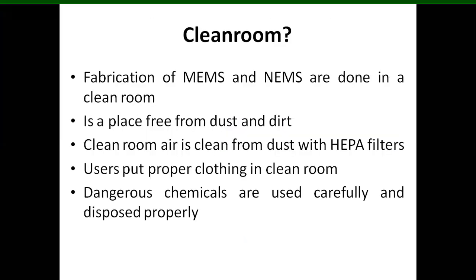Okay, next is clean room. Fabrication of MEMS and NEMS, that is micro fabrication and nano fabrication, are normally done inside a clean room, a place free from dust and dirt. Clean room air is cleaned from dust with a HEPA filter. HEPA stands for high efficiency particulate air filter.